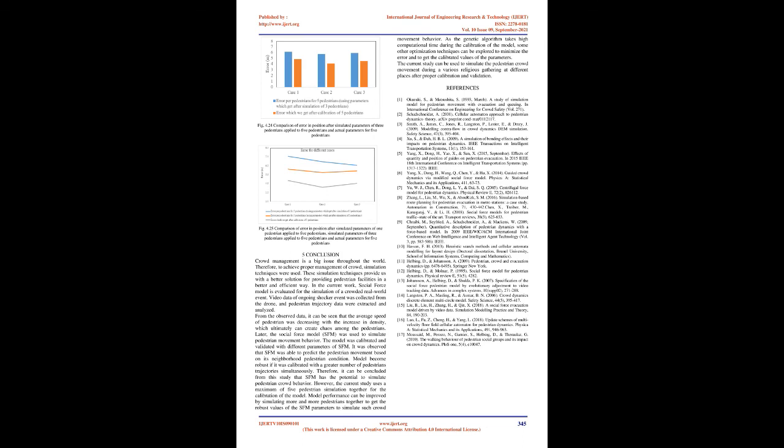Later, the social force model, SFM, was used to simulate pedestrian movement behavior. The model was calibrated and validated with different parameters of SFM. It was observed that SFM was able to predict pedestrian movement based on its neighborhood pedestrian condition. The model becomes robust if it is calibrated with a greater number of pedestrians' trajectories simultaneously. Therefore, it can be concluded from this study that SFM has the potential to simulate pedestrian crowd behavior.